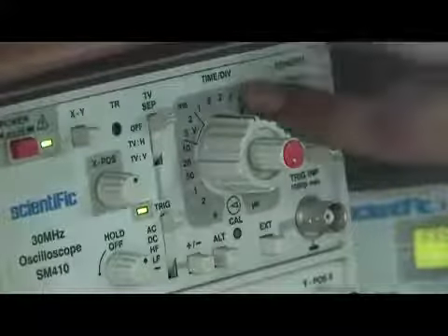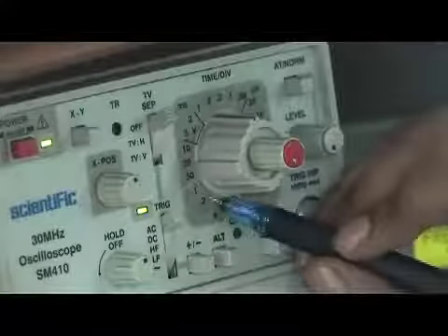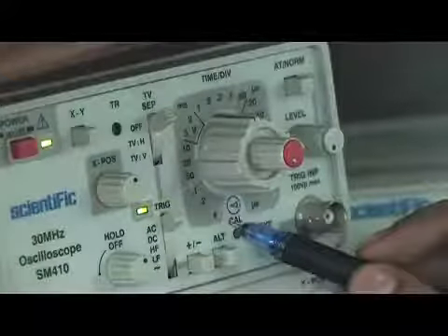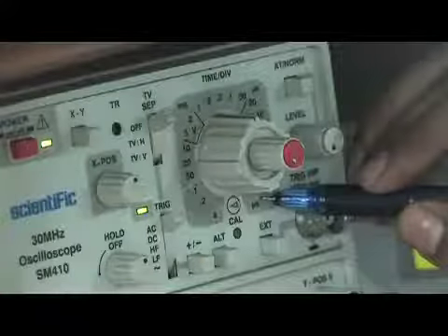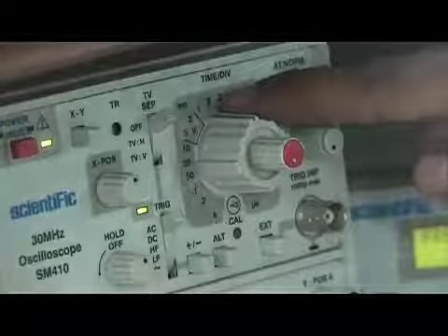So it is 2 into, where you can see this knob lies, there is a line, this one, it lies at 0.5. So 2 into 0.5 is how much? 2 into 0.5 is 1. What will be the unit? From this gap till this small gap, between these, the unit will be in milliseconds. From this gap to here, the unit will be in seconds. From this gap till here, the unit will be in microseconds. But right now we are in the millisecond range. That's why it is 2 into 0.5 milliseconds.